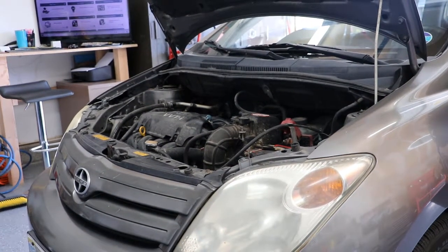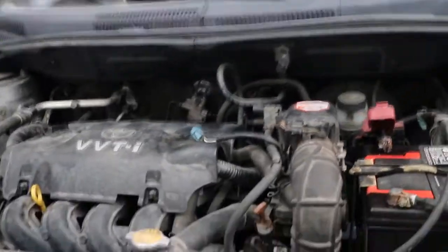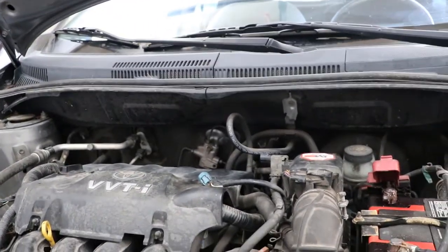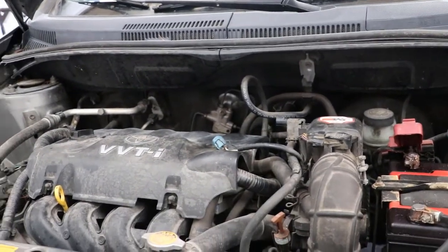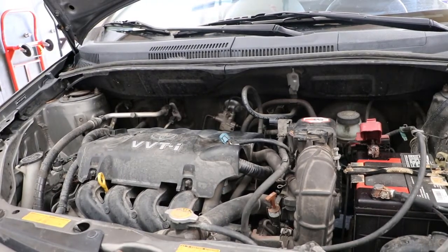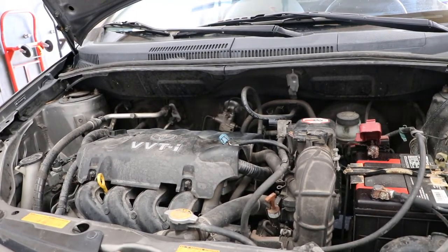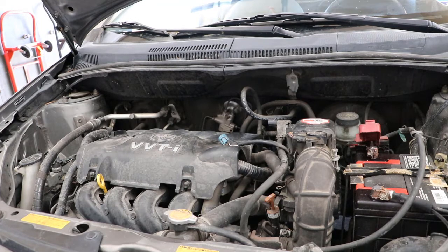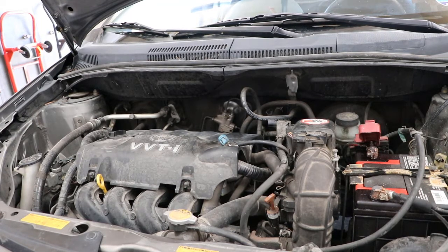Alright guys, so this is what we're going to do. I didn't record it, but I did do the test already, but I'm going to record it for you guys so you can see what I did here. I wanted to check to see if the system itself is holding pressure. So I came here to my diagnostic tool, I turned on the evaporative emissions vacuum switching valve, which activates it, closing the valve when it's activated, which means the system can hold pressure.